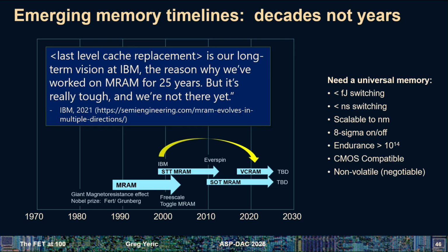And that's architecturally what you do to optimize for the fact that even with SRAM, you can't place all the data you want. So you place what you think is going to be important in lower level caches. And then when the chip needs a piece of data, you go look for it in the first level cache. And if you can't find it, you stop and go to the next level. On a nanoscale, it's a massive, massive delay. But even the last level cache works in the many megahertz range, so from a chip operation standpoint, you still get what you need done.